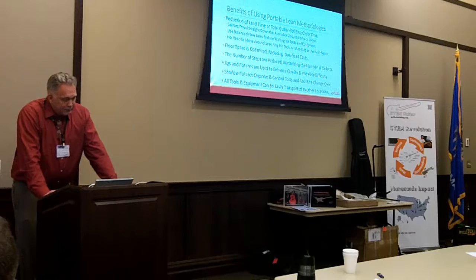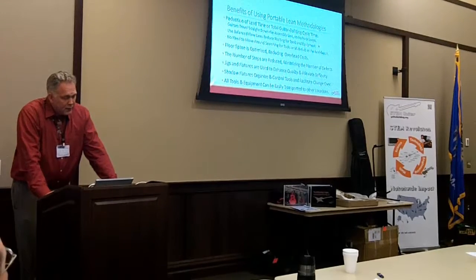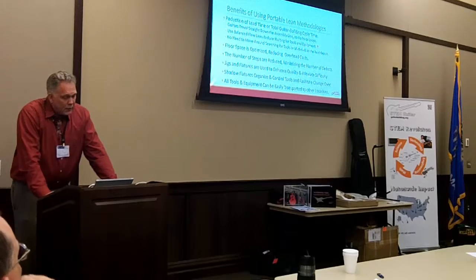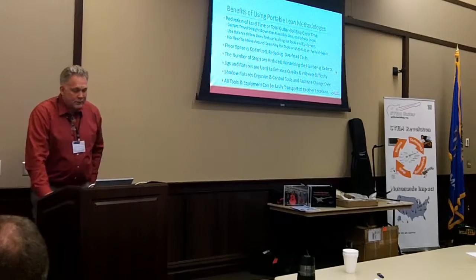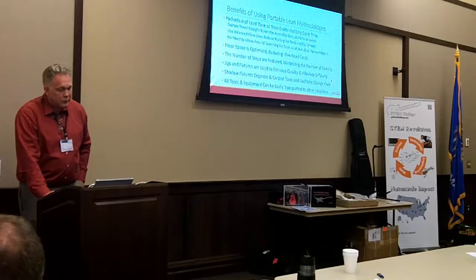So what are the benefits? Reduction of lead time or total guitar building cycle time. Guitars travel straight down the assembly line, no forks, no loops. We use balanced flow lines to reduce waiting for tools and equipment. No need to move around searching for tools or materials at the workbench. Floor space is optimized, reducing overhead costs. The number of steps is reduced, minimizing the number of defects. Jigs and fixtures are used to enhance quality and alleviate difficulty. Shadow fixtures organize and control tools and facilitate changeover.